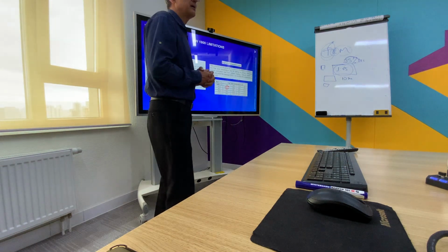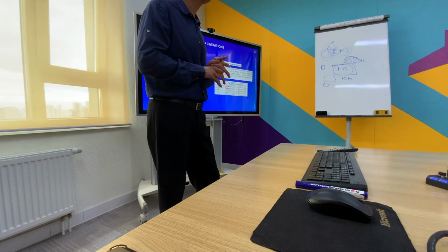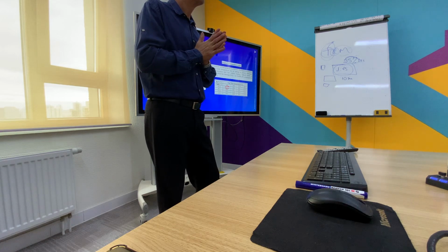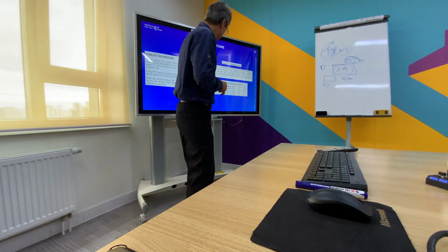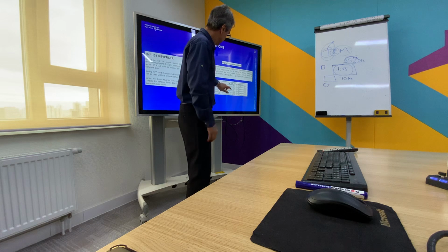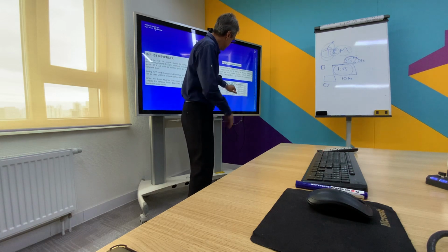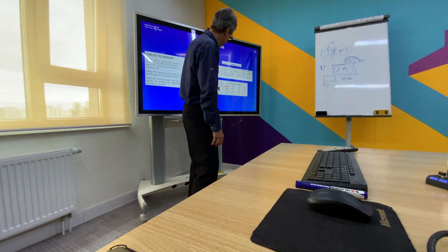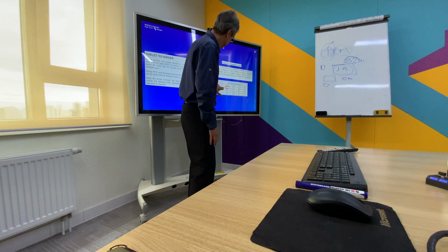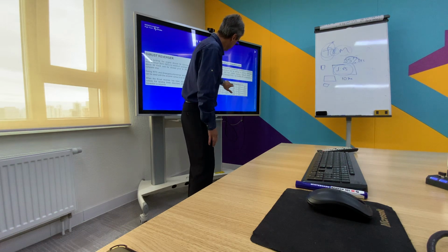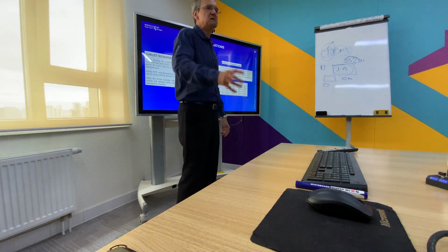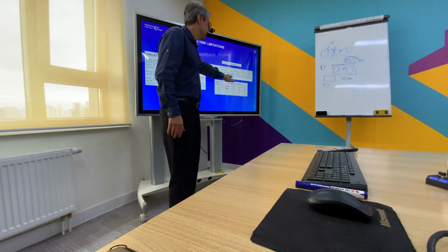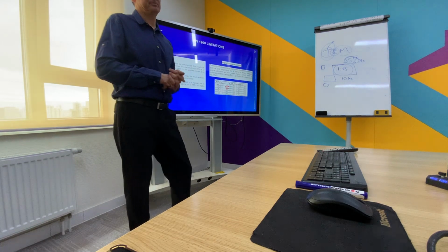So imagine that in winter time here, it's minus 40 degrees. Minus 40 is around here, right? And the fuel tank maybe around minus 29 degrees. So to get this message here, the fuel temperature in fact must be around 30, almost in the limit to get this message. So in hot temperatures, we hardly ever have this message on the engine warm-up.